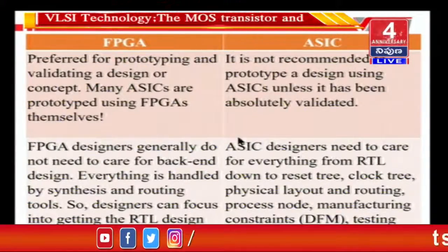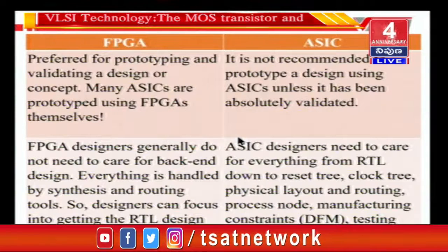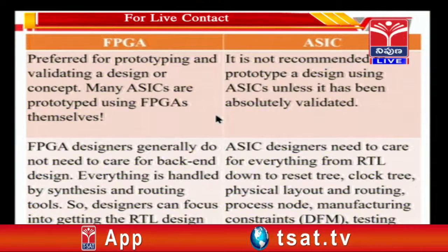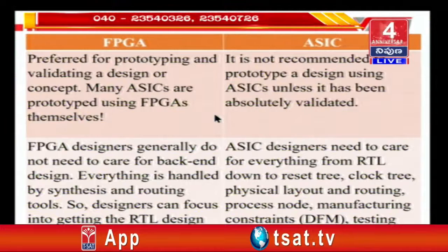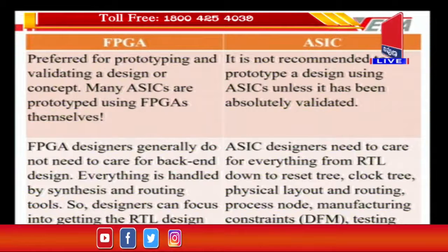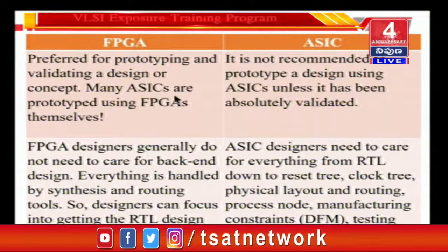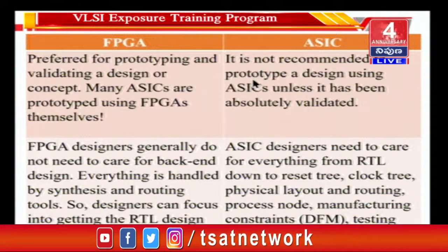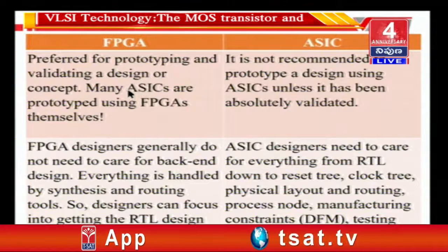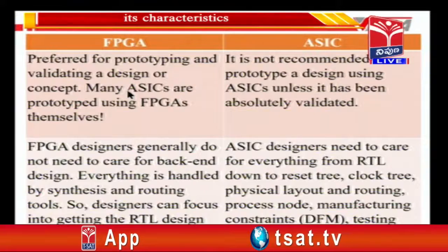And the last of the slides is that FPGAs are preferred for prototyping. When you are developing an ASIC and you want to go in for manufacture, one of the first things that most organizations do is use an FPGA for verifying the functionality of that ASIC. So while comparing FPGA with ASIC, we are saying that FPGA is used for verifying the functionality of an ASIC in silicon. Mind you, verifying the functionality can be in simulation or it could be in silicon.